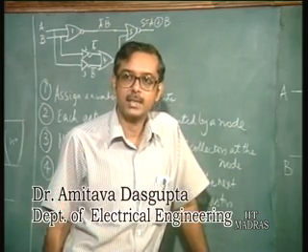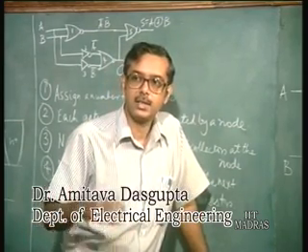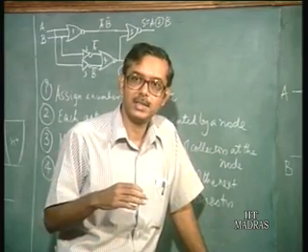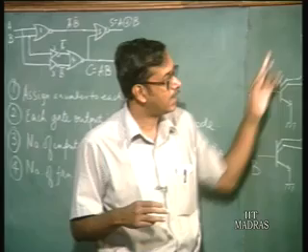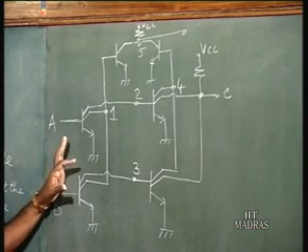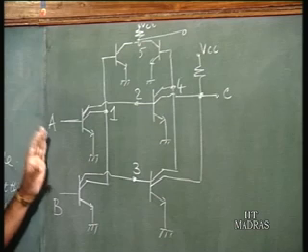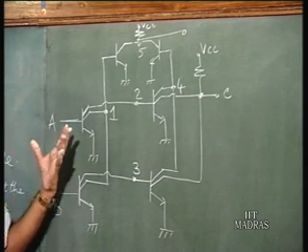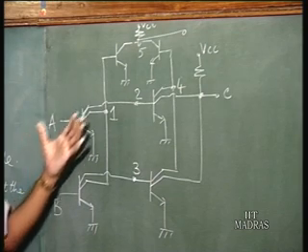Whereas in TTL, for example, just one single gate requires so many transistors. So, with just 6 transistors you have made a half adder. You can look at the savings in area when compared to TTL. I mean, it's really great.